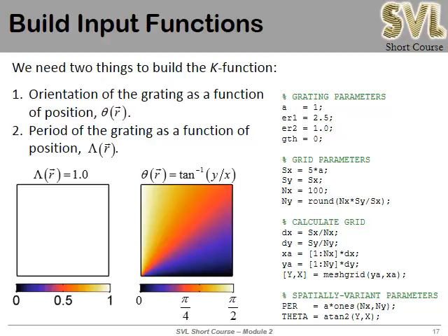So the first step in this, and we've connected it to some MATLAB code on the right, and of course we also have the computer sessions that write very similar code. But at the beginning, we will build our input functions. I'm not showing the fill fraction function here, I'm only showing period and theta, but we'll define two-dimensional arrays to define period and orientation.